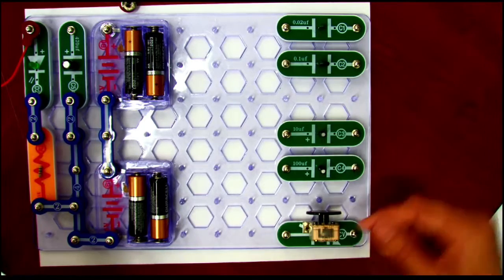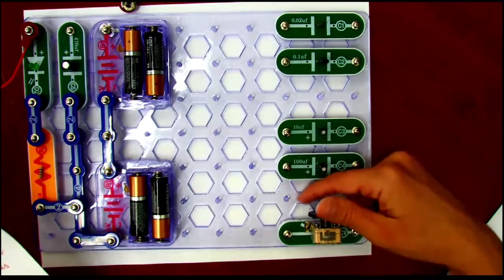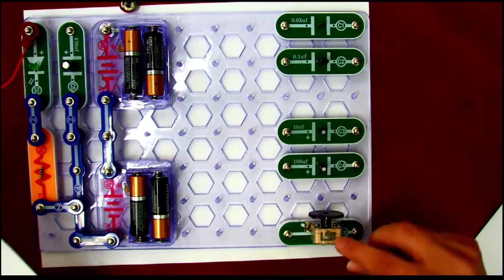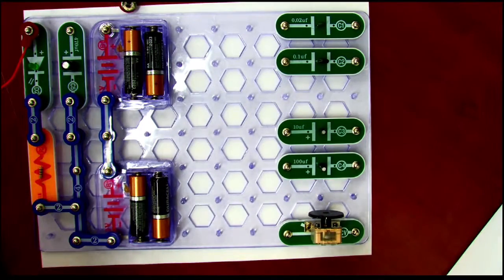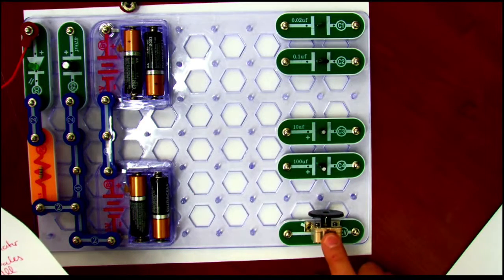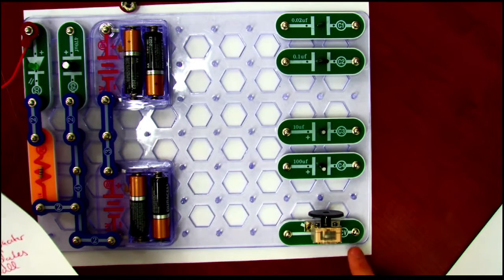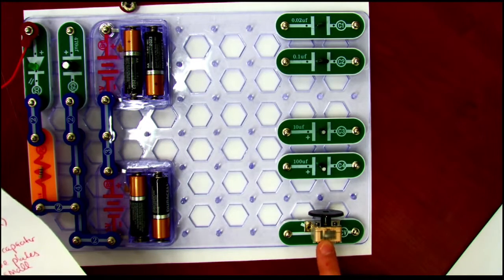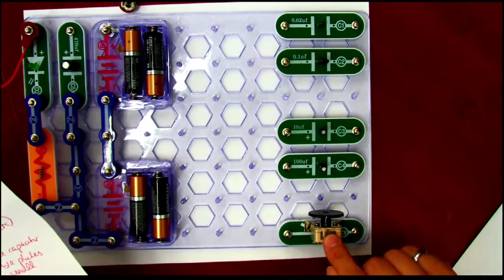And then this guy's a variable capacitor that you can turn the little knob on. You can kind of see into that window. I'll pass it around for those of you in class. It moves some plates in there, changing how much they're overlapping, to have those 2 plates standing off from each other. And this is for very, very small capacitances. It goes to 4 times 10 to the minus 5 microfarads, or to 2 times 10 to the minus 3 microfarads. So very small numbers of capacitance, but you can vary it, and this is used for high-frequency radio work.